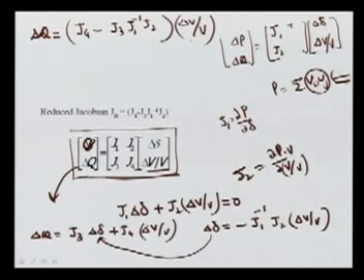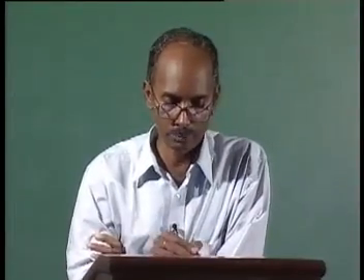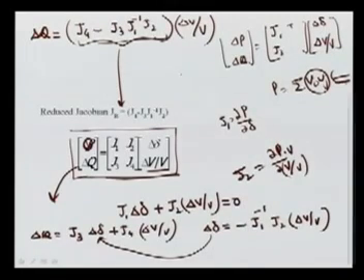V. This is called JR, the reduced Jacobian, and it gives information on the change in reactive power with the change in voltage at any bus. So this reduced Jacobian gives a lot of information about system voltage instability. Normally for voltage stability analysis we use this Jacobian rather than only J.